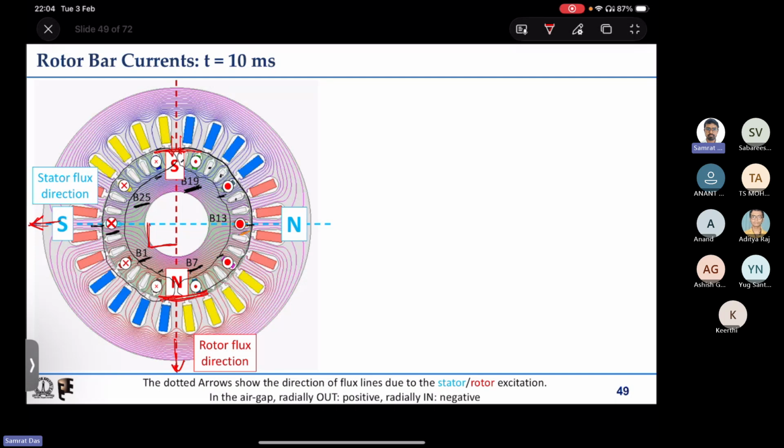So you can see that in an induction machine, when the rotor is running very close to synchronous speed, where we can neglect the rotor bar inductance with respect to the rotor resistance, then ideally we can have quadrature shifted magnetic fields. Now let us try to understand which case this is, motoring case or generating case, by looking at the relative phase of the two magnetic fields.